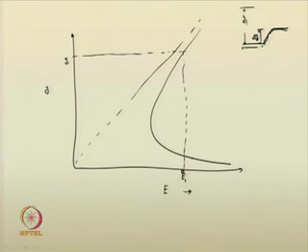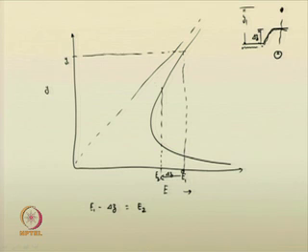At E 1, you subtract del z, that is E 1 minus del z, and you will get the corresponding value somewhere here. That will be the specific energy at the upstream section 2. This is given as E 2 and the corresponding depth of flow is y 2. Okay.